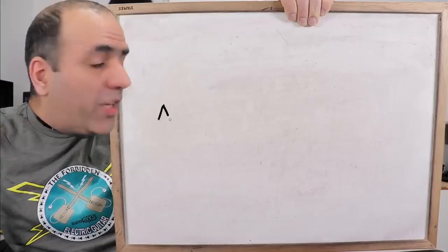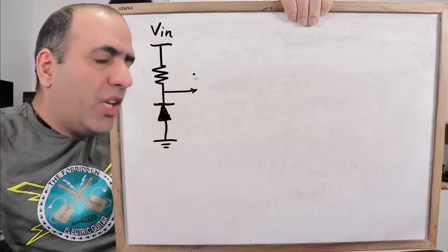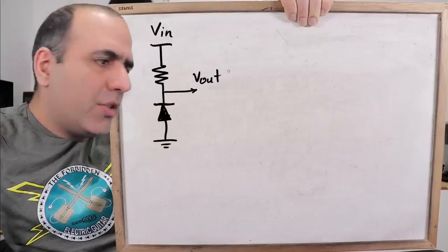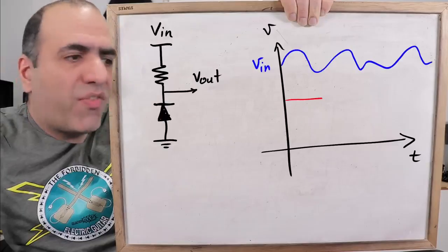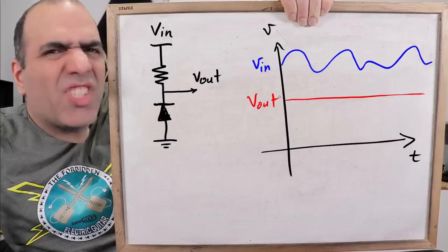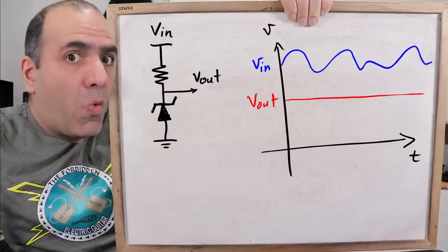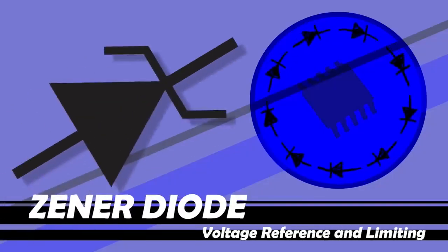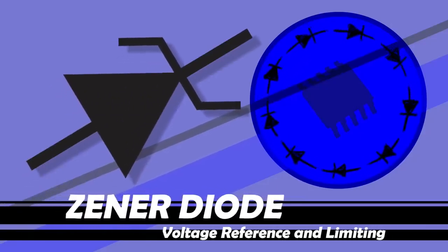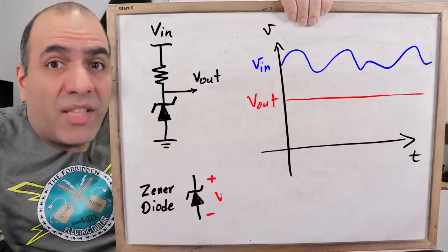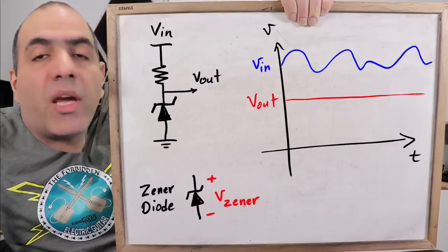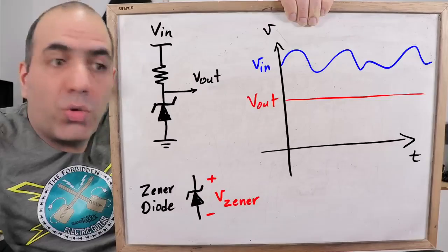Until it is. We can make use of breakdown voltage. If it is a reliable known voltage, we can use limited current through it and create an almost fixed voltage, typically used as a reference voltage. And so we make something called a Zener diode. Zener diodes are designed to have specific breakdown or Zener voltages, like 1 volt, 5 volt, 10 volt, or whatever.